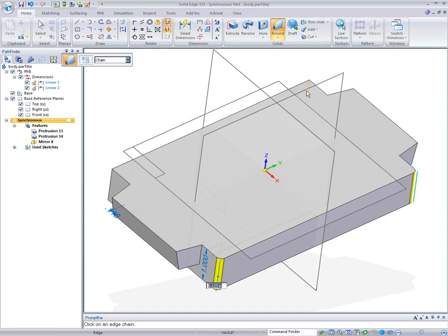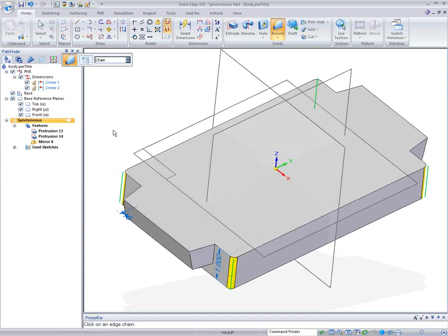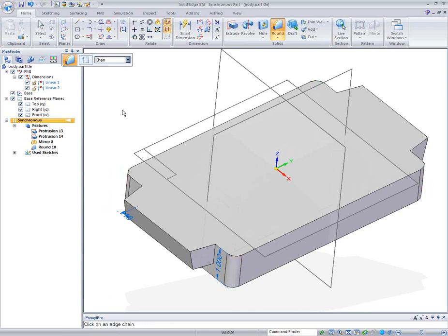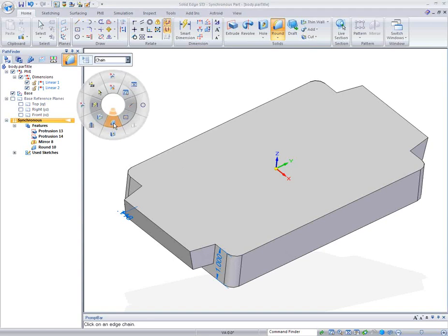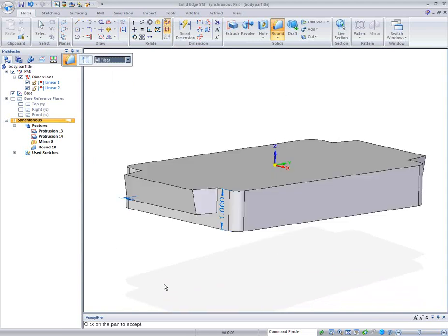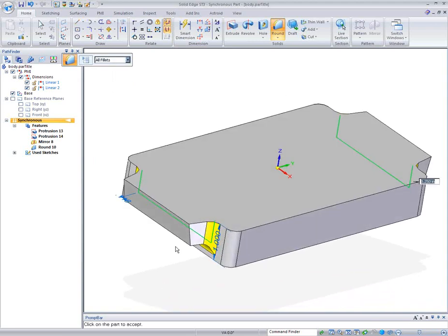Now, many people, when they work with a product such as this, will go out and take these corners, and they'll maybe make them a 1/4 inch and start to break corners. Don't know if you're aware of this or not, that you can also go out when you set something like this, and you can just say, I want to take all fillets. So I'm going to take all of the fillets, and it's going to go out and set itself to 0.01. Just kind of break those edges down a little bit.